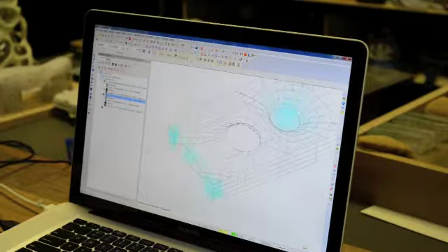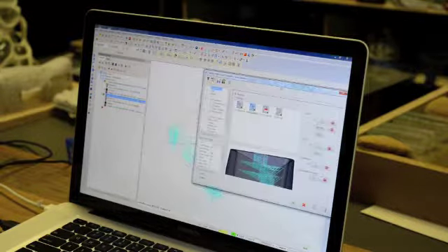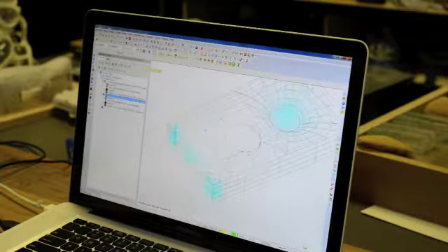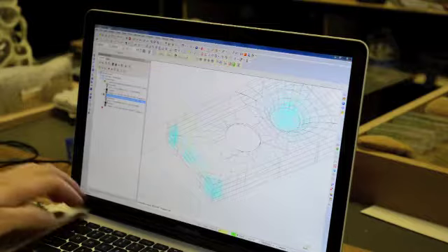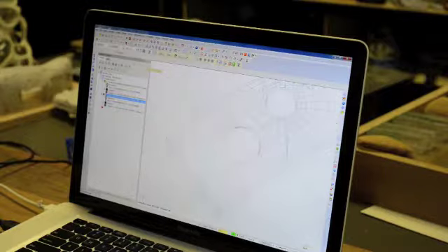So what we saw was that we missed two surfaces in the drive selection, so it actually cut down to the bottom of the stock, so we need to reselect and make sure that we have 3 surfaces instead of 1. So how we did that was we went to the parameters folder again, and you just click on drive, and then